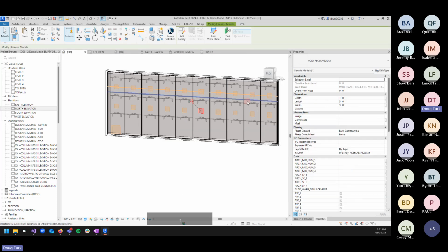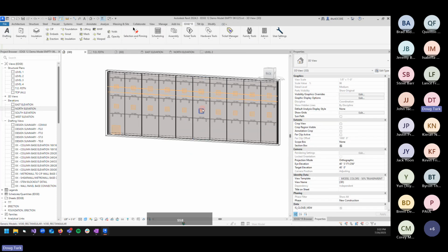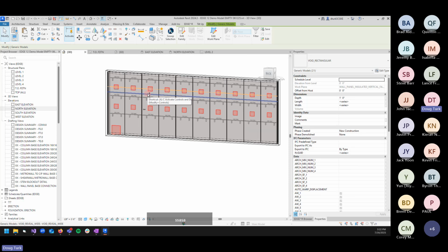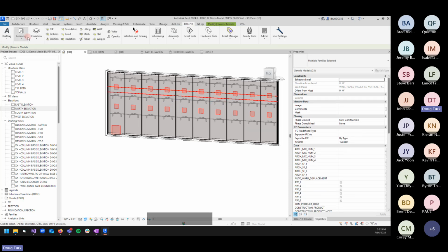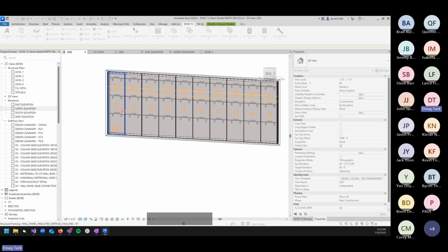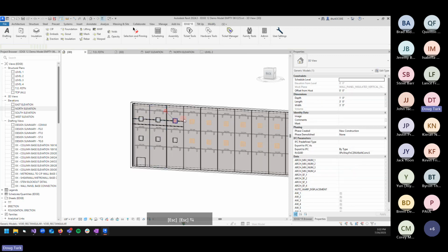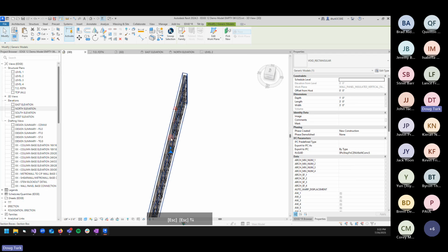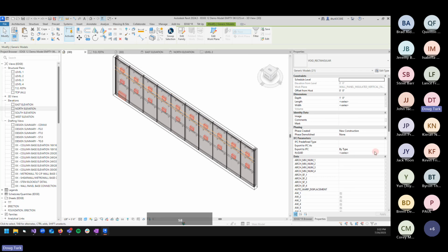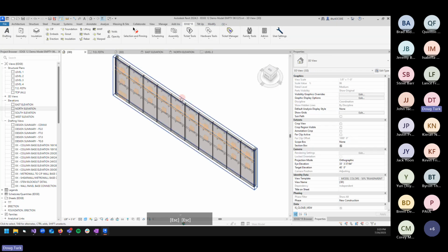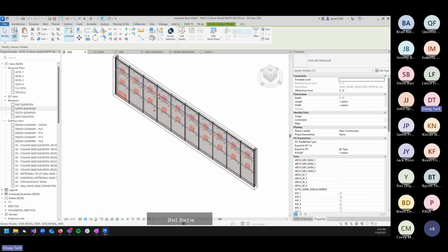So we're going to go ahead and select all of our rectangular openings. And then we're going to select all of our reveals. And then we're going to run the tool I was talking about before, the multi-void cutting. And then we're just going to click on down the line. And I'm realizing now that I probably didn't fix the depth on these. Yep. So we're going to hold on a second on that. And then we're going to select these, make their depth 14 inches because we're dealing with the 14-inch panel. And now we'll do that part.